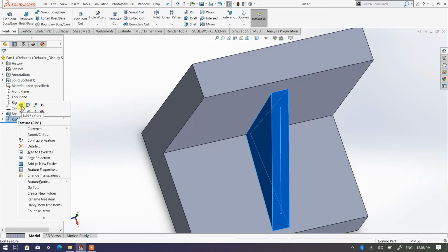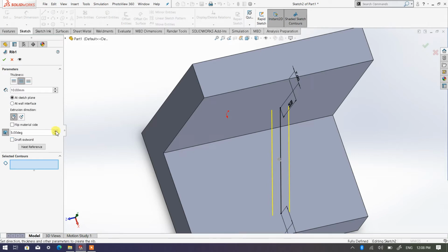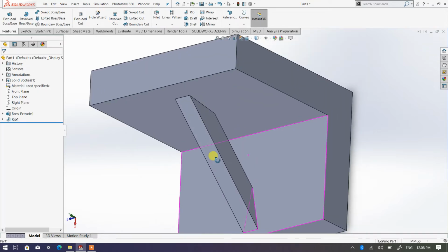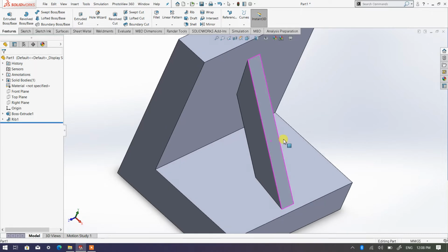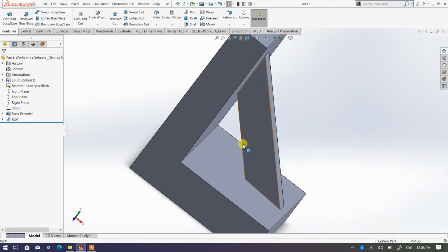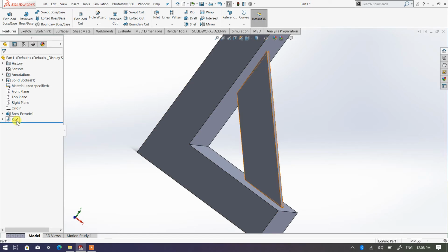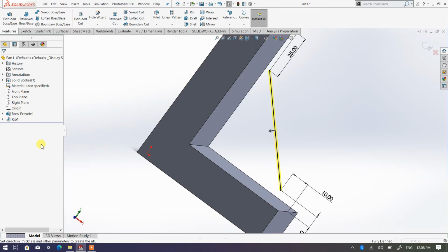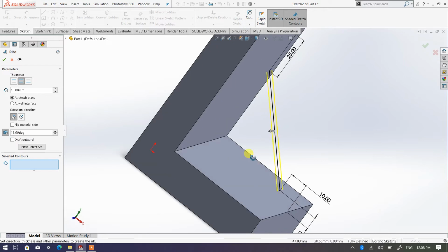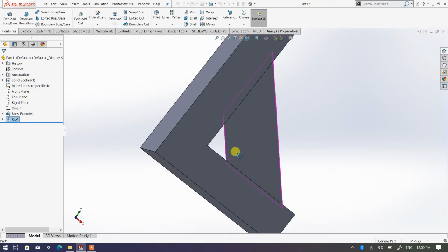Okay, let's say I'm going to change this one. I'm going to increase it a bit to 10 or 15 degrees. Click OK. Oh, there you are. So it means that the draft will go like that. Since I already indicated 15 degrees, that's why we do have holes over here. If I reduce this, we do have holes just now, right? So let's say I'm going to make it 10. Let's see how it looks. Click OK. They still have holes.